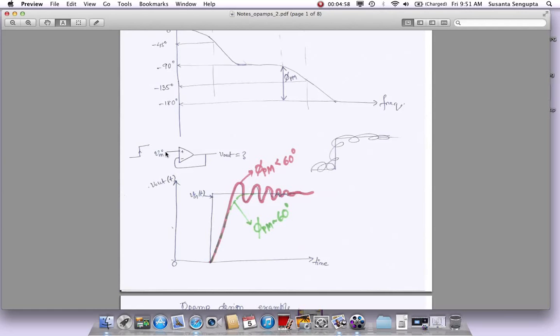If you take the square wave case, square wave is the worst, because anytime you have a fast rising edge, like a clock, I'm only showing a rising edge, but let's just refer to one particular edge only, that corresponds to high frequencies. If it was a clock of some frequency f, and you do a Fourier analysis and expand it in the frequency domain, it will have frequency components of f, 2f, 3f, 4f, 5f, and goes on. It'll have it till infinity.